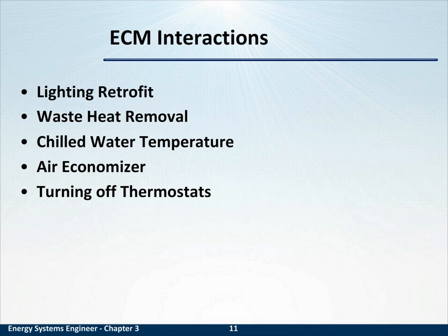And then the ECM of an air economizer. Often airflow is higher in economy mode and can cause pressurization problems. The relative humidity can swing back and forth inside as easily as it does outside. That can cause problems with people sensitive to humidity, arthritic, and it can cause problems with equipment.